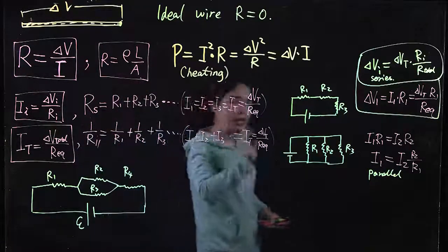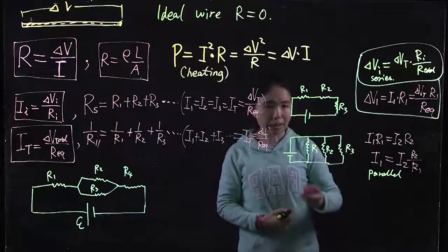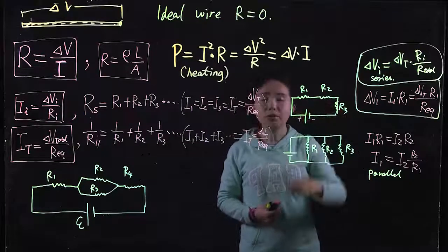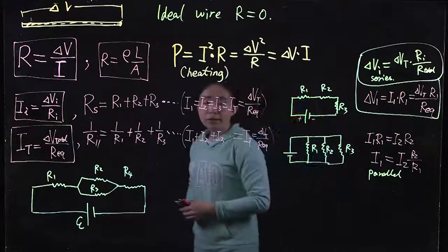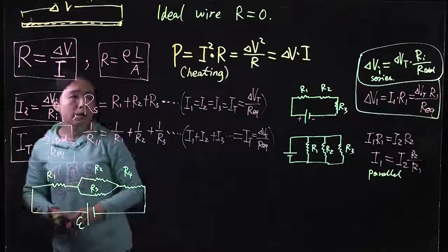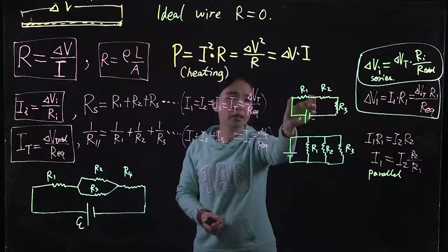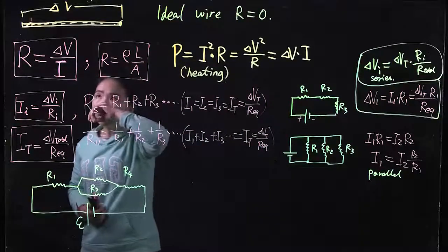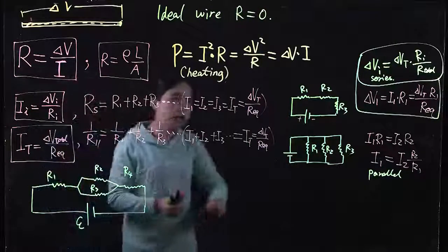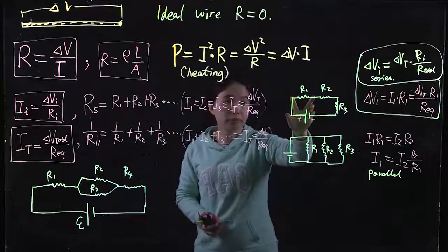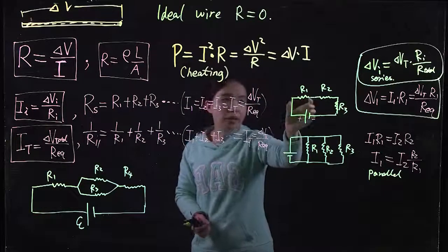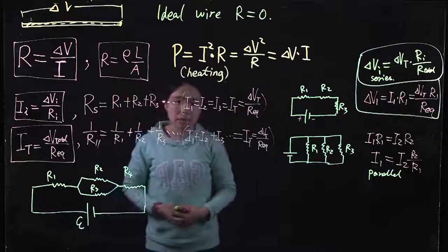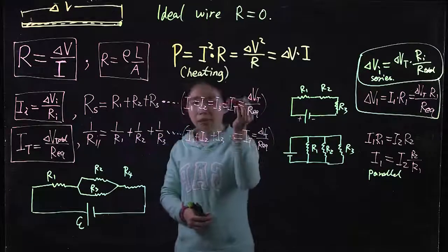And what is resistance going to do for us? Basically, if we apply a voltage with a battery, with positive here and negative here, this voltage is going to provide current in your circuit. And if we know the voltage difference across one particular resistance, then we can know the current. In order to measure the resistance, we measure the voltage difference between these two points, that's delta V, and we measure the current going through this part, that's I, and the ratio of that is your resistance. Your resistance for a particular resistor typically is a constant.